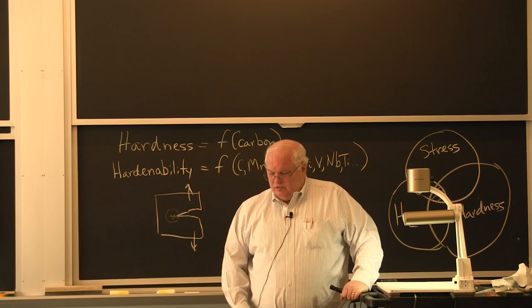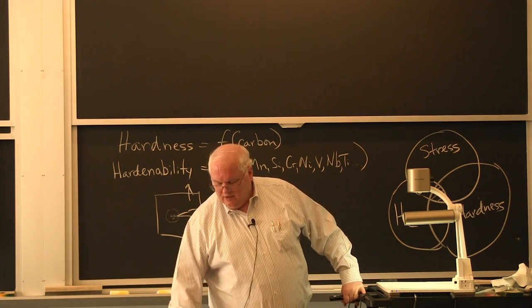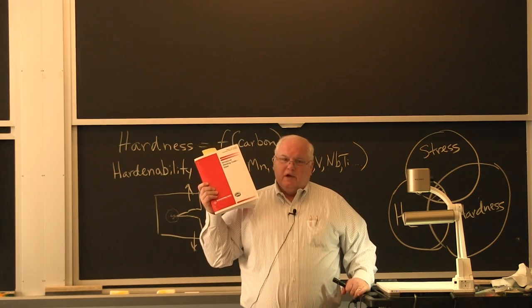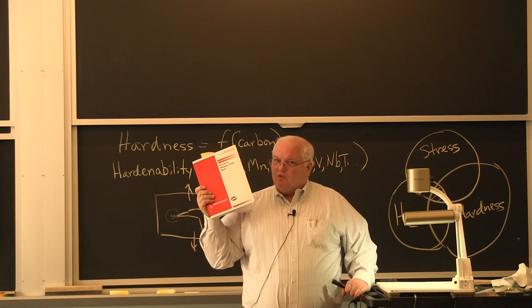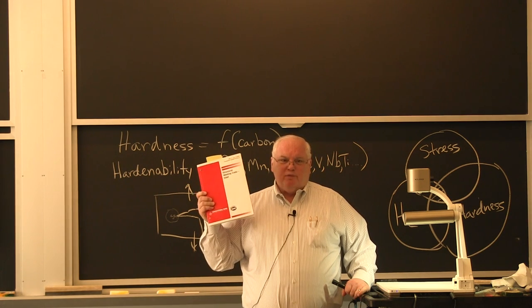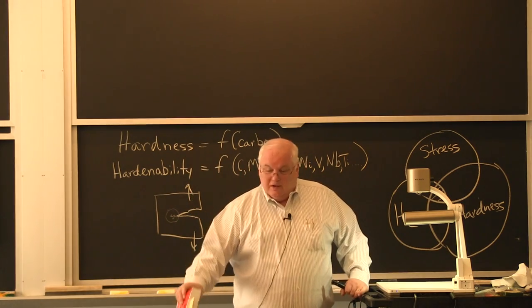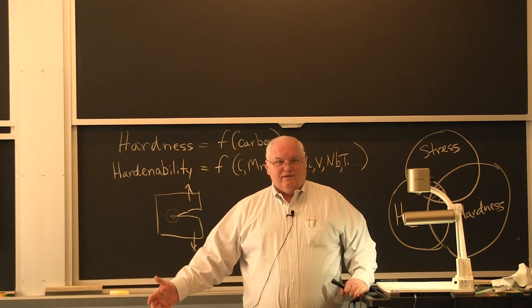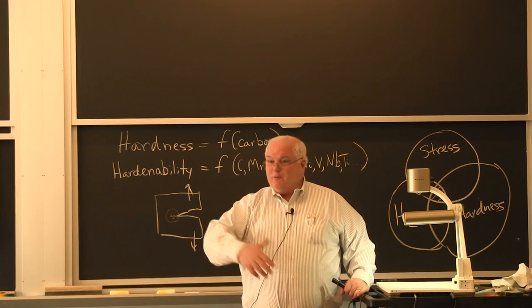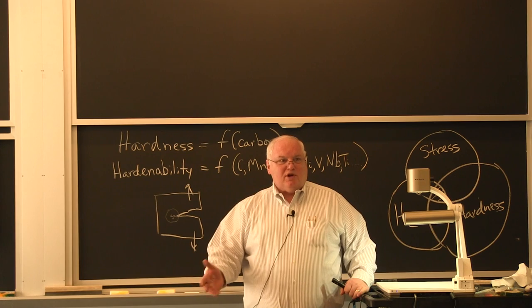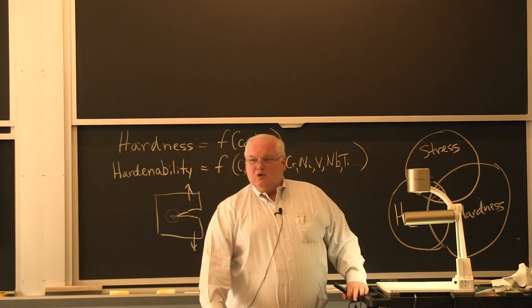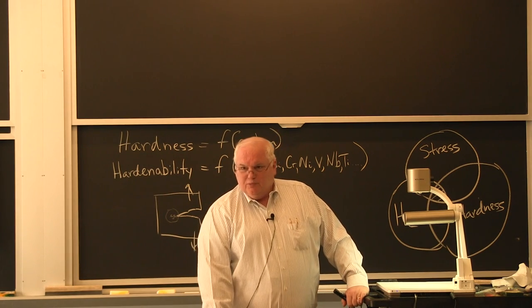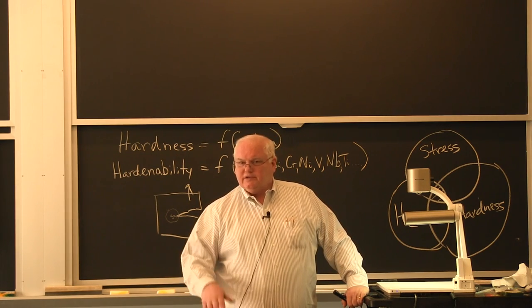It turns out if I go to one of the welding codes, and I'm talking high-strength steels for bridges, this code requires that you not test for cracks in your welds until 48 hours after you've made the weld. Why? Because if you test within the first hour, you might find no crack. And a couple hours later, there might be a crack, and you just missed it because you tested too quickly. You have to sit for 48 hours before you can do your non-destructive testing if you're building a bridge or a building out of 100 KSI steel.